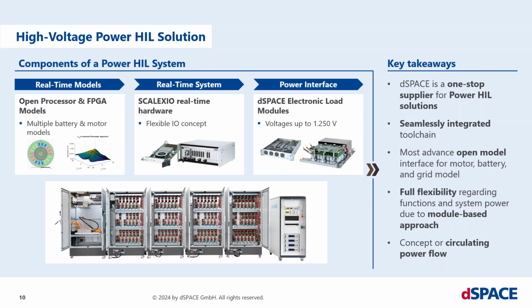The next major component are real-time systems. I already mentioned the Scalexio environment. Real-time system means I need a system which is able to calculate these real-time models in real time. So if I have a very, very slow processor which is not able to run these models in real time, this is not useful for our power hardware in the loop solution.